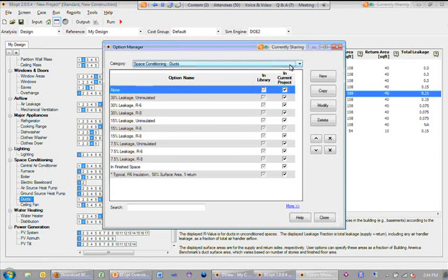The last guy I talked to wasn't real familiar with the duct blaster procedures, but we typically measure two things: the total leakage, which just uses the duct blaster on the duct system, and then leakage to the outside, where we pressurize the house and the duct system to the same pressure. Obviously that's the important leakage. So there's some leakage around the registers and grills, which is irrelevant, but that is part of your 15% leakage, isn't it?